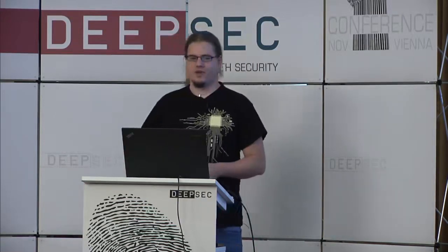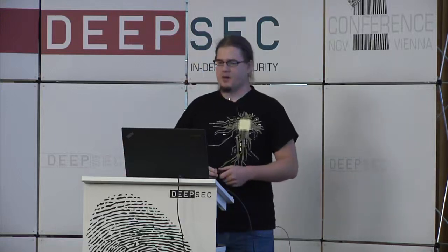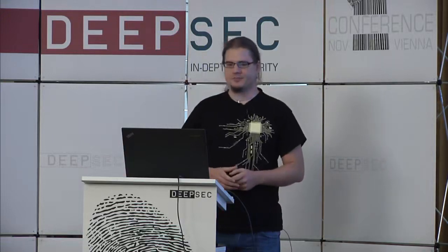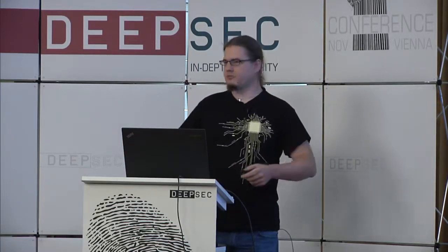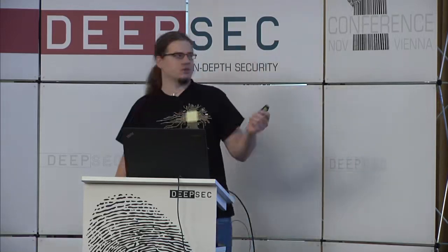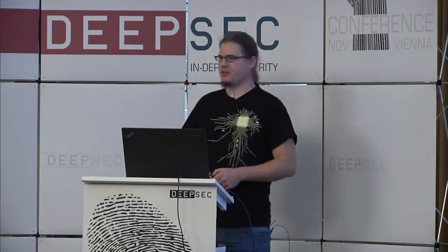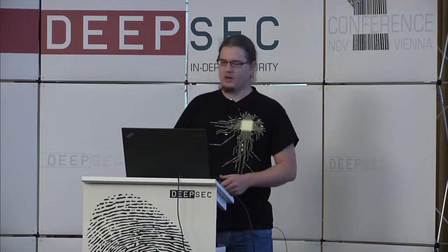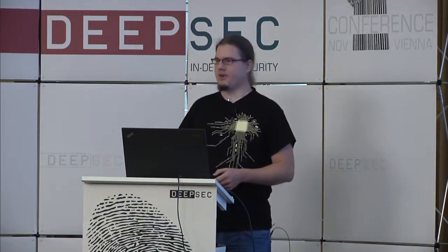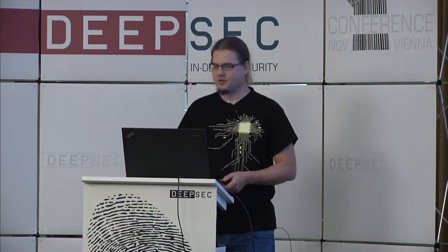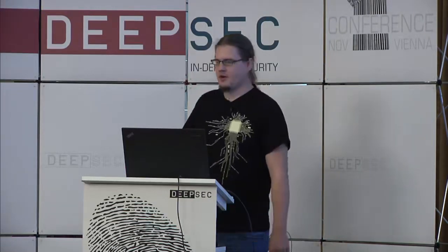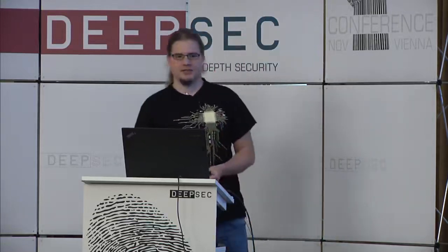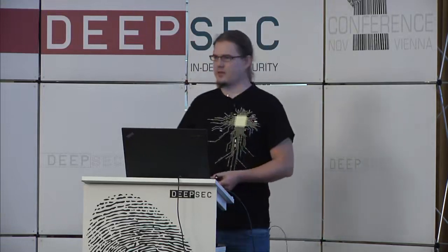Once we get the firmware, at least for the nRF24, we can load that into IDA Pro. It's an 8051 compatible instruction set. We can start disassembling and read more documentation. There's also an SDK available from Nordic Semiconductor, the manufacturer of the nRF24 chipset. And you can look around, try to compile code, write your own code, and reverse it. Last but not least, the radio-based analysis. Of course, it is a wireless desktop system, so we can have a look at the wireless spectrum.